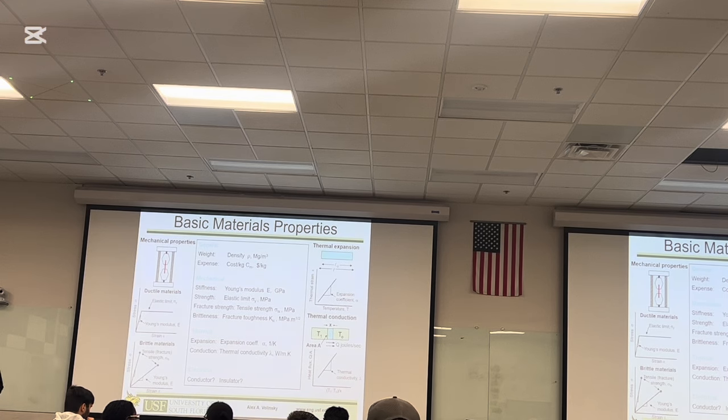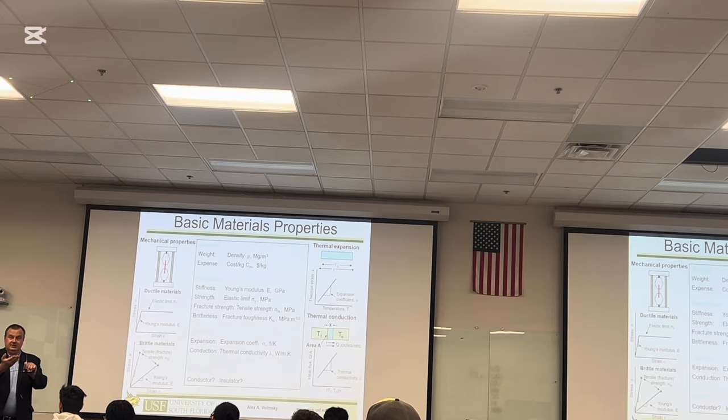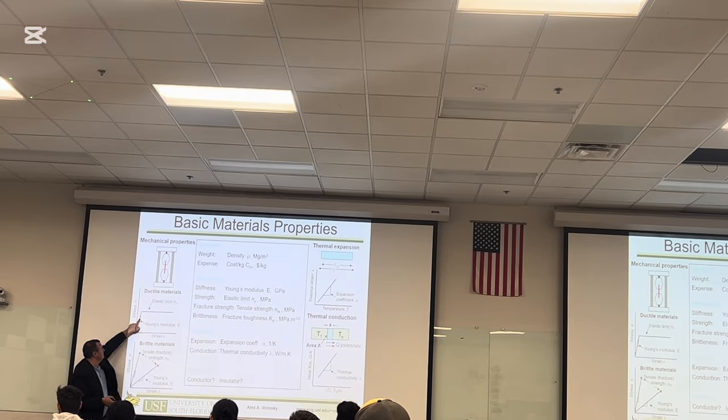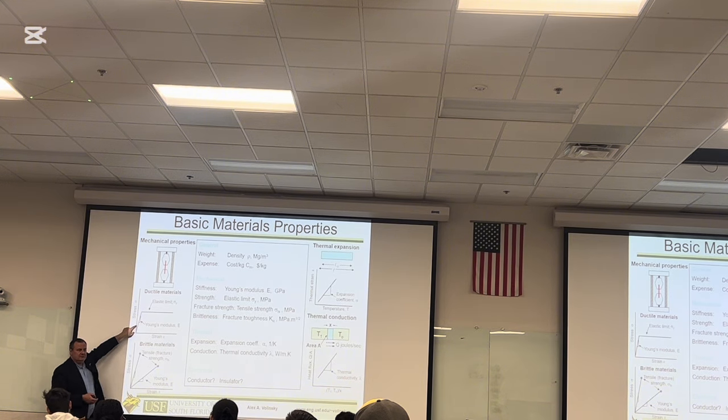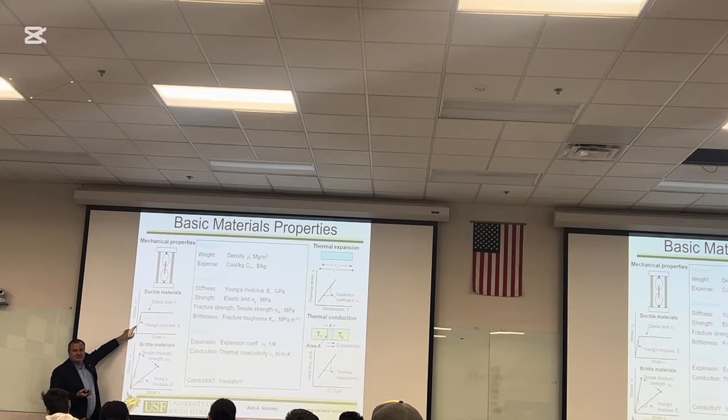All right, I'll use this business card instead of a paper clip. What I'm going to do is bend it 90 degrees. You see I bend it 90 degrees? And I'm going to let go. And it restored its shape, right? So what kind of deformation do we have during load? Well, obviously we have elastic deformation, meaning that it's recoverable. So if we're anywhere here, we're going up and down, and that's what you want. That's primarily what would be your design, to have an elastic deformation.